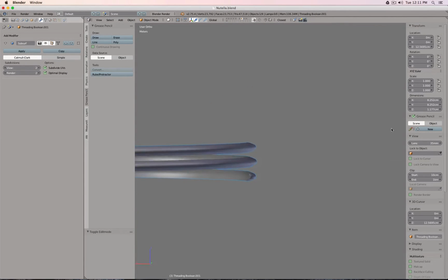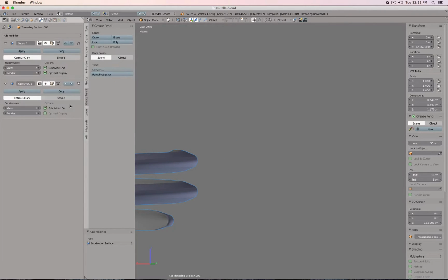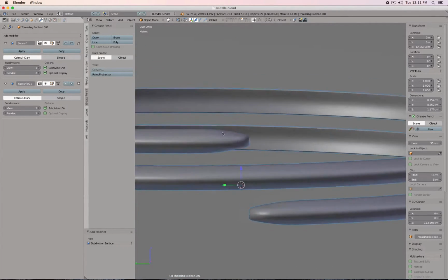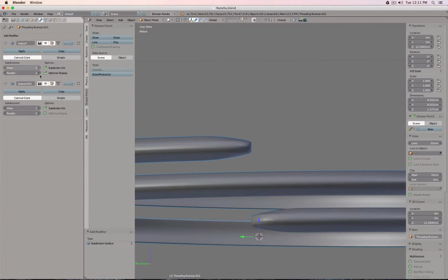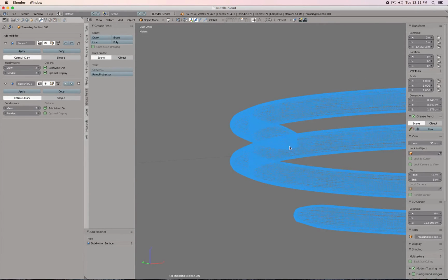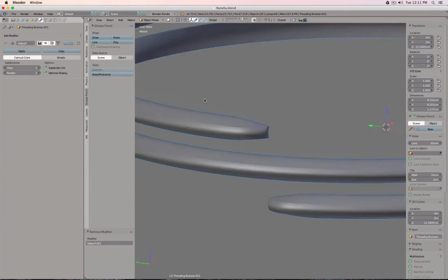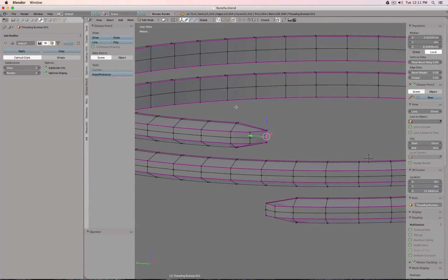So you see we dome this part a little bit. And we could even at this point maybe do a double subdivision, smoothing again. There, see, now we actually get a nicer, crisper look this way. However, this is an insanely dense mesh. You don't really want this to be used for Boolean operations, so something like this still is more than sufficient.